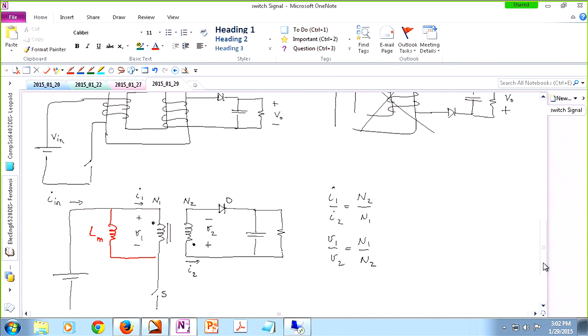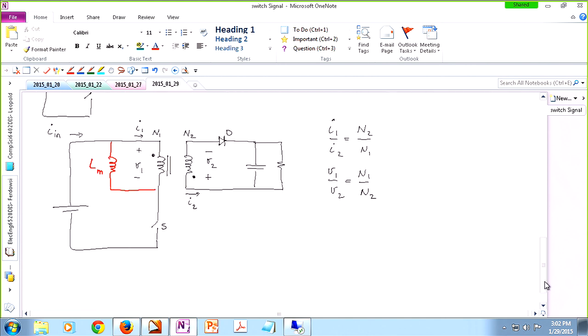All right. So the classic assumptions that we used to make are still holding, like all the components are ideal. We are analyzing the system under steady state conditions. The output capacitor is large, therefore the ripple in the output voltage is not much, or the output voltage is almost DC, and we saw in simulation it's not that big a deal, we can easily achieve that. And we are analyzing the system under continuous conduction mode. So the current of the magnetizing inductance is continuous.